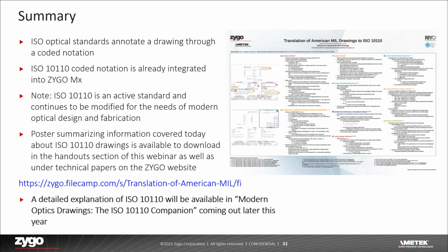So you could, but you also want to tell the fabricator what you're going to look at so that you can make that comparison. If you're using one comparison standard, it might be slightly different than another. So you can write on your drawing whatever your comparison standard is or equivalent, and that's just to let the fabricator know, this is how I'm going to look at the end part.